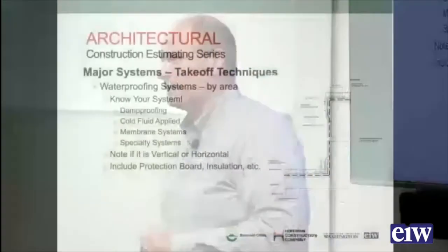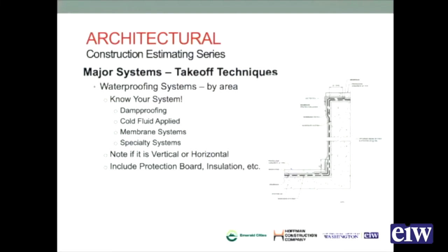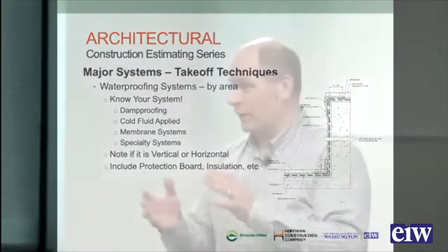This system here that you see, this is a PVC system that you see on underground light rail stations. It is an extremely thorough system where you actually embed PVC strips into the concrete and then weld PVC sections into it. It also has a bentonite system associated with it as well. It's a belt and suspenders system that is definitely on the expensive side. But you need to understand what it is that you're dealing with and what the components are, because